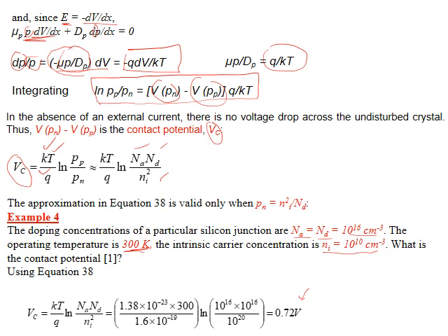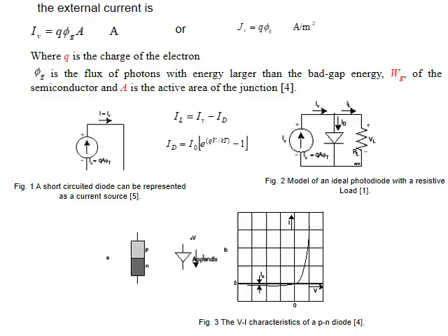By the way, you need to know, just for a sense, that the cell voltage is supposed to be in this range, 0.7. If it is lower than this, it means that the quality of the cell is not good enough. You can judge the quality of your cell, and one of the simple ways is to see the Vc. If it is 0.7 plus or minus in this range, it is okay. But if it goes to 0.6, 0.5, this means the quality of the cell as manufactured is poor.